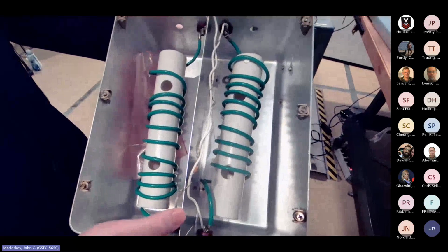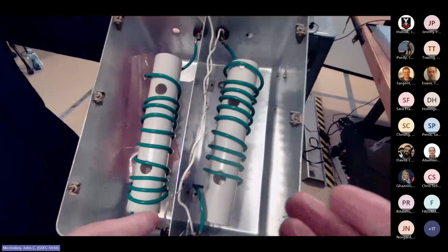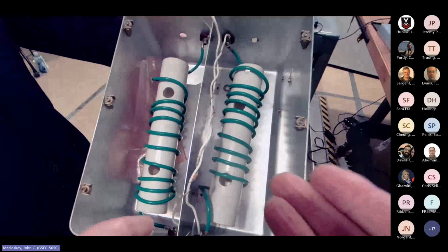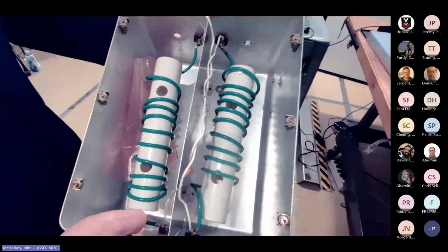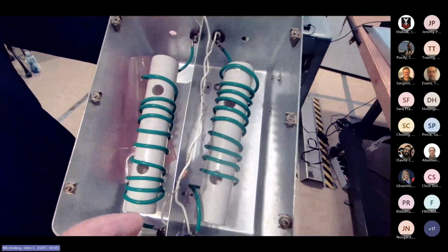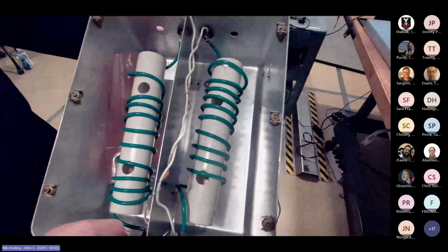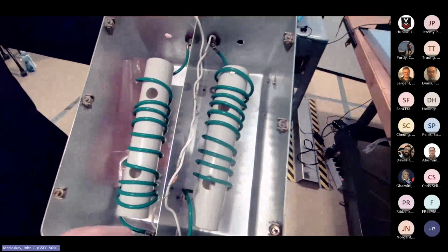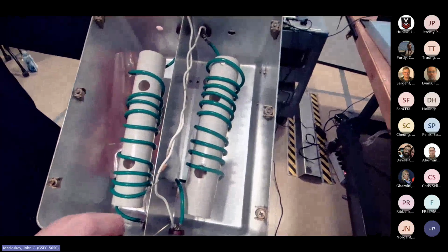And we got it to the point where, okay, if we were going to use this thing to test any hardware, maybe it's good enough for a first try. But you start getting into resonances and stuff like that at those higher frequencies that I would put a big asterisk next to any test results that I got with this thing. Because it could give you some really weird results above 30, 40 megahertz when those resonances kick in.